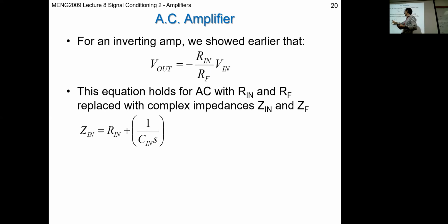So that means that you have dynamics in this capacitance. The resistor doesn't have any dynamics, but the capacitor has dynamics associated with it, a differential term. Or in fact, in this case, it is actually an integral term, because it's adding up charge. It stores charge, then it releases it. That's an integral function. It adds up the charge over time and stores it. So the 1 upon S you have in this function is basically indicating an integral effect.